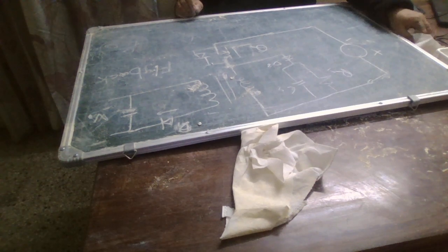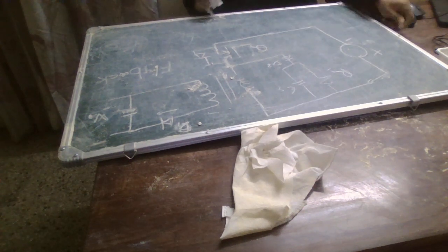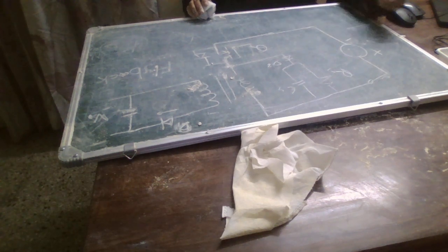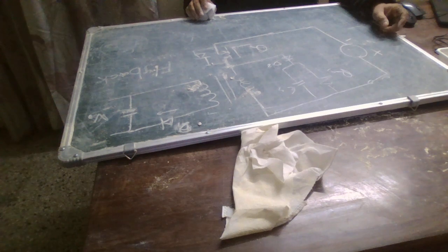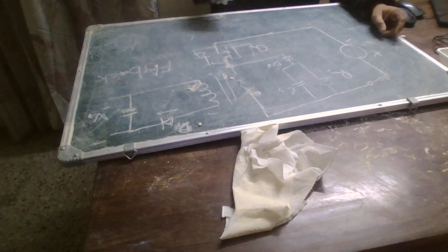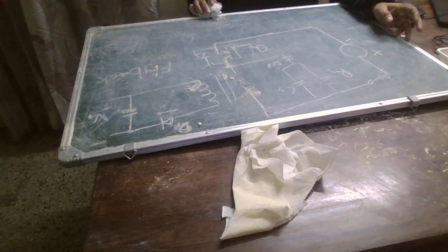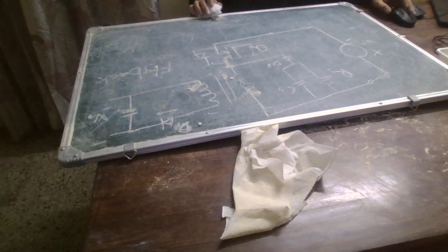Now we have to be very careful here. In the forward converter, which I won't be covering because I have hardly used it, though the half bridge configurations are based on the forward converter, when the switch was turned off we need some current path to dissipate the energy stored in the magnetic core. We can use a snubber, or we can also use a reset winding.